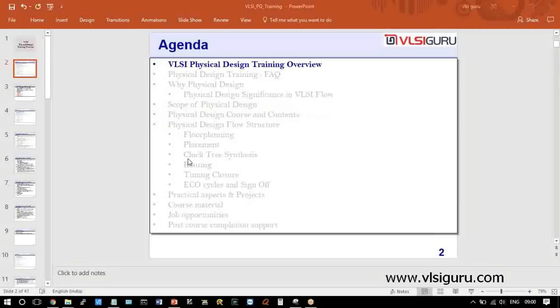Now, after writing the code, there will be a team for functional verification who will write the same code in their own language, because the code that we write in HDL is supposed to match the spec. For example, if it is a Bluetooth spec or a DDR spec, it's supposed to match that. If it is not matching, that's going to be a problem. So there will be a functional verification team, using OVM, UVM, SystemVerilog and all that. They will make sure that the code written in RTL, in Verilog or VHDL, is compliant with the IEEE standard based protocol.